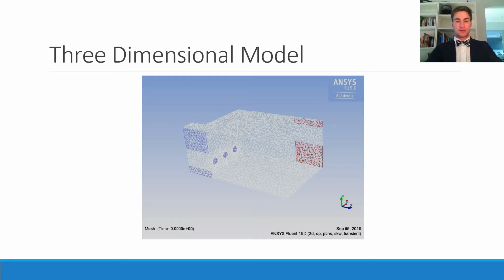The zone has 3 A-recycle pumps. From left to right, they are numbered 1 to 3. The A-recycle pumps are all duty, and an even runtime is managed to ensure even wear. During the collection of physical data, one A-recycle pump was operating. The flow rate from the A-recycle pump resulted in a velocity of 0.832 meters per second.